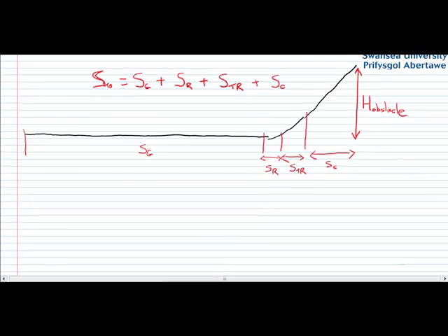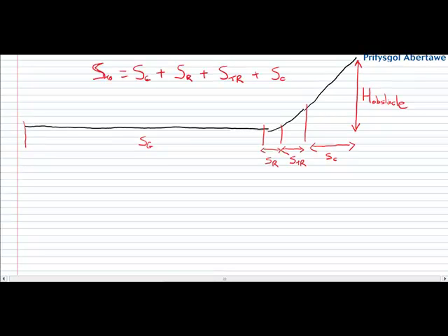Now we've already defined the takeoff velocity, sorry, of your given aircraft in a previous lecture as being 1.2 times the stall speed. That's a pretty good estimate of the velocity at which your aircraft will take off. And of course, already at this stage in the design process, you've got an estimate for the stall speed of your aircraft.